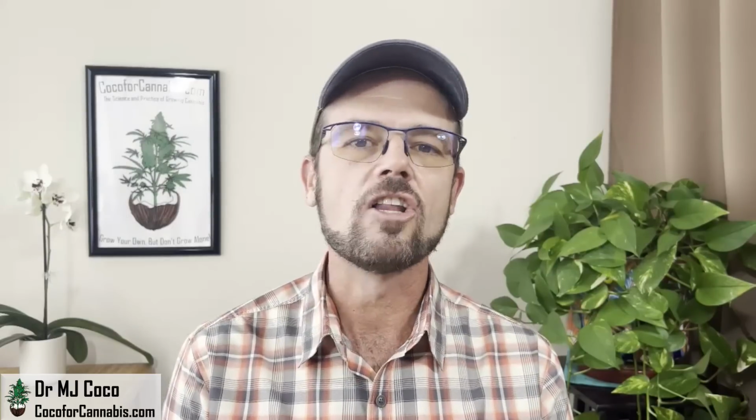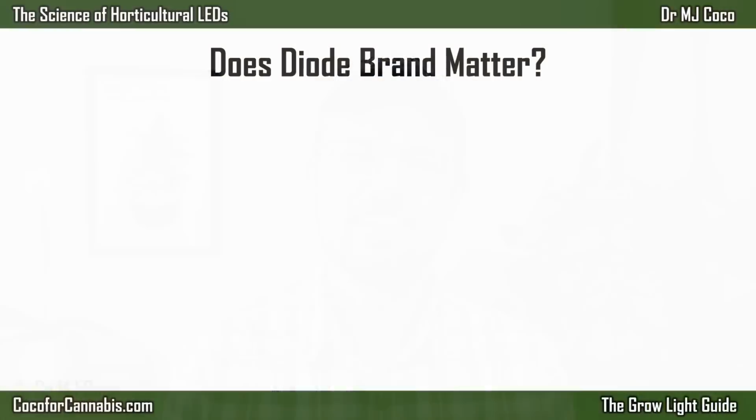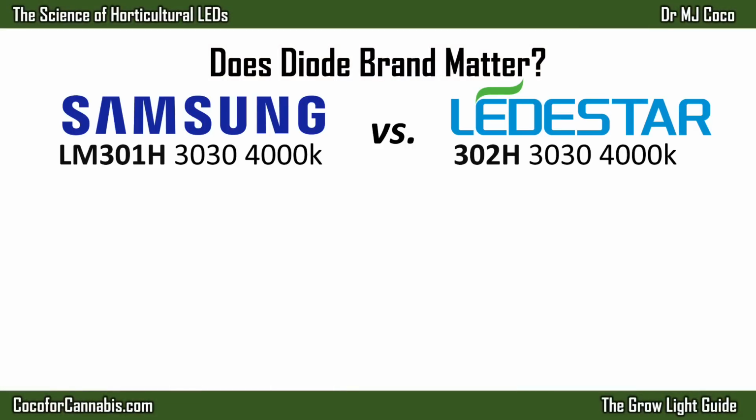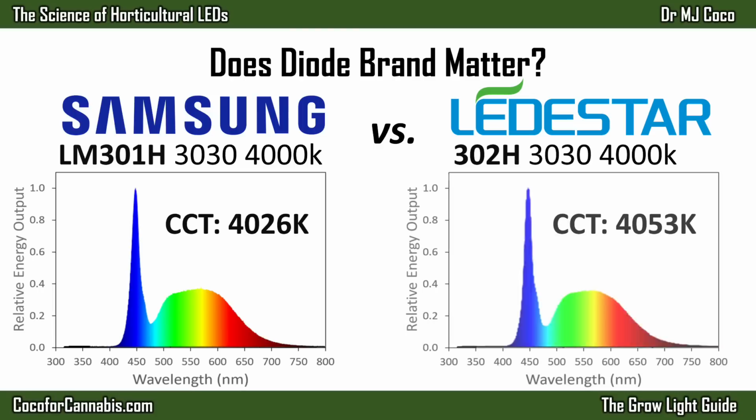Now maybe you think the color or spectrum is different between the Samsung and Lettistar diodes. Both sets of diodes were labeled as having a combined color temperature of 4000 Kelvin. The Samsung diodes tested at an average color temperature of 4026 Kelvin. The Lettistar diodes averaged 4053 Kelvin. On the human scale, 4000 Kelvin is between daylight and soft white. It's pleasant to work under and shows true colors, unlike Blurple light.